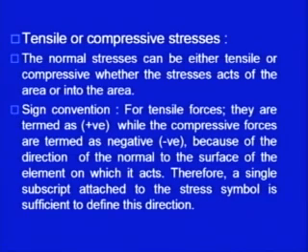Because of the direction of the normal to the surface of the element on which it acts, we are always considering the same sign, plus for tensile and minus for compressive forces. Therefore, a single symbol, because you see these are all axial, means the line of action of either the tensile or compressive force is along the same axis. So we only need a single subscript to define these types of stresses. That's why we are not going for a two-axis or three-axis subscript to define the nature of the force.